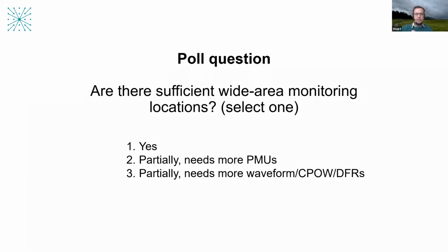So they're going to stay important, but particularly with all the power electronics coming onto the system and these higher frequency oscillatory behaviors in particular, as well as the other transient behavior, continuous point-on-wave is important now and is going to become more and more important in more and more grids. What form that takes, exactly how we fit it in, whether we're doing things like streaming, I think in the immediate term anyway, it's unlikely we'll be streaming all continuous point-on-wave measurements to a central location.